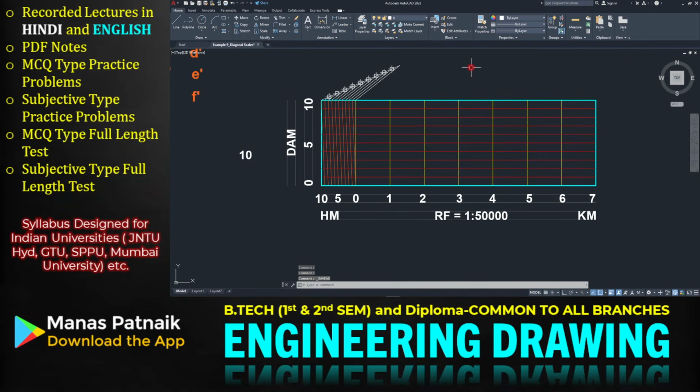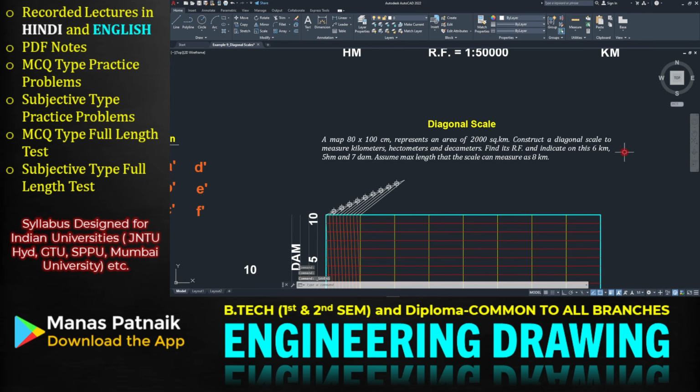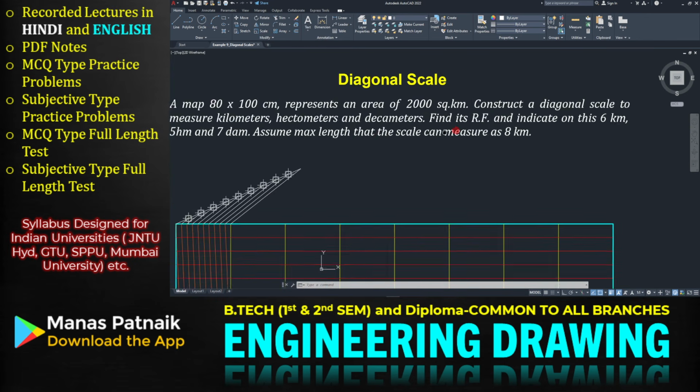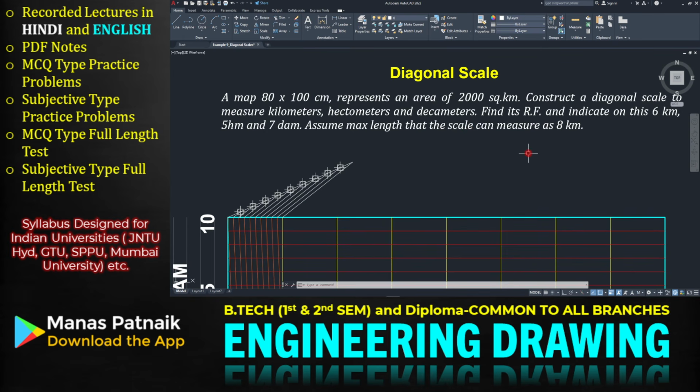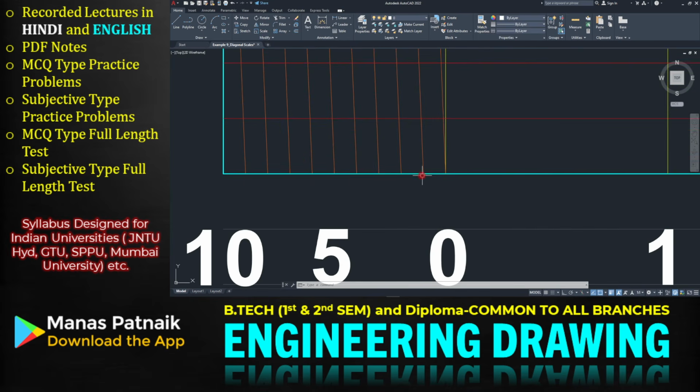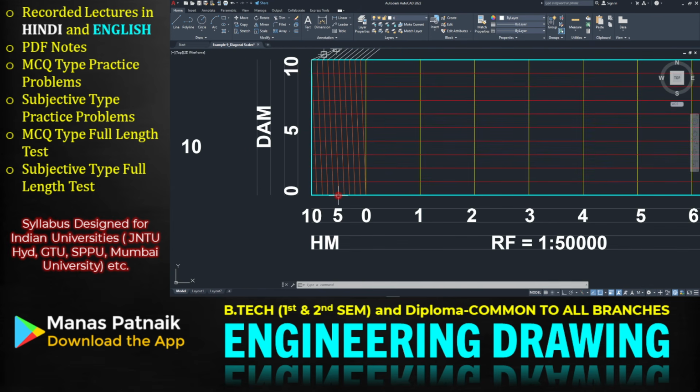Is there anything remaining? Yes, sir. You need to represent on this scale a distance of 6 kilometer, 5 hectometer and 7 decameter. Okay, so this can be done. This is 6 to the right of 0. 6 kilometer, 5 hectometer, and 1, 2, 3, 4, 5 hectometer, and 7 decameter. 1, 2, 3, 4, 5, 6, 7.